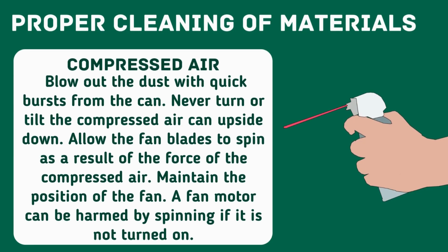Never turn or tilt the compressed air can upside down. Do not allow the fan blades to spin as a result of the force of the compressed air. Maintain the position of the fan. A fan motor can be harmed by spinning if it is not turned on.